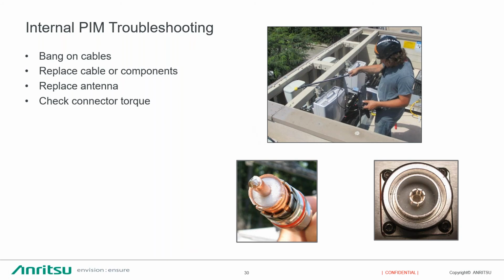So in terms of whether you have to climb the tower for this, well, yeah, you do. But at least you know that it's internal and you're not going on a wild goose chase across different places and different things. Your site might still be live, but you've just turned off the sector so that no one gets radio burn. So just follow the safety protocols when you get to this point of troubleshooting internal PIM. Everyone's got them, so I'm not saying anything that anyone doesn't know here.